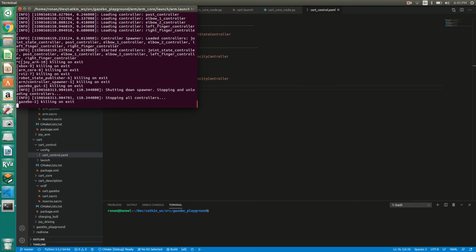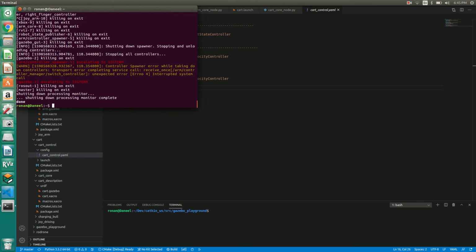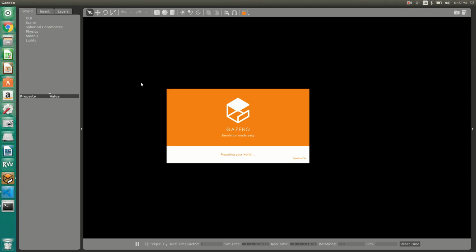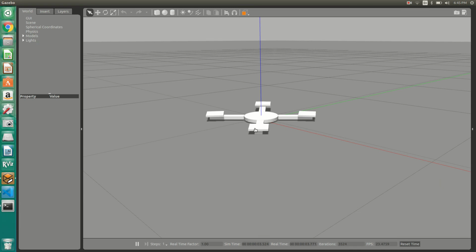This is going to be something I tackle far in the future, because getting the Gazebo world simulated time to sync up with any sort of controller operating at over 100 Hertz that I set up will require a lot of overhead to get those clocks to talk to each other synchronously and reliably. So right now, all I have is a plugin I've written for Gazebo to apply a force proportional to the speed the rotors of the quadcopter are going. As you see here, these rotors are really just there for visual representation.